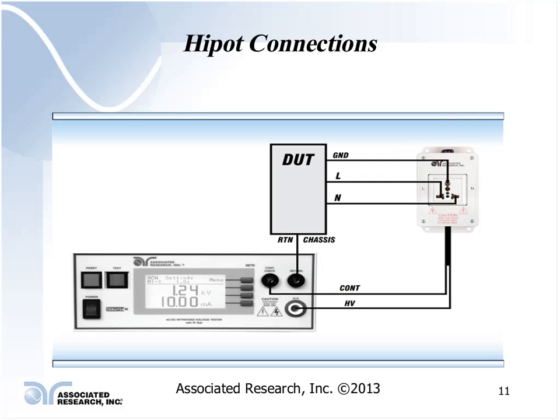The whole purpose of that ground within your product is to provide a low resistance path for any fault current to flow that will cause the circuit breaker or fuse to trip to protect you against an electrical shock hazard. It is there also to make sure that the resistance is low enough that no voltage will elevate high enough to cause a high enough potential on the enclosure that would create a shock hazard also.